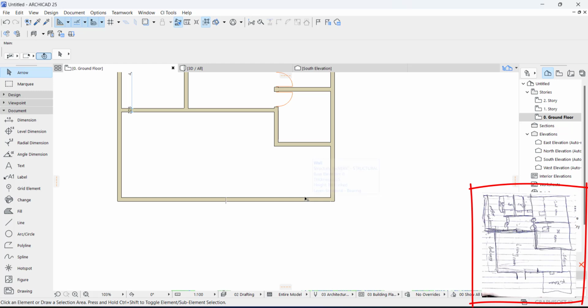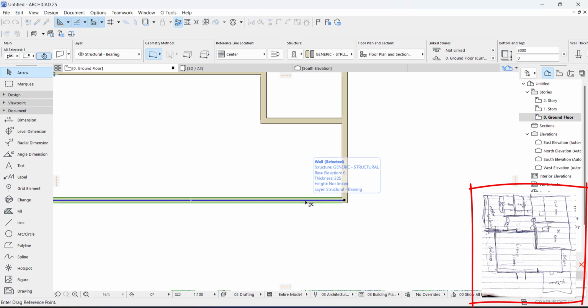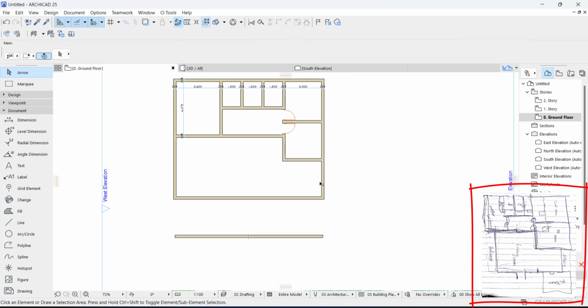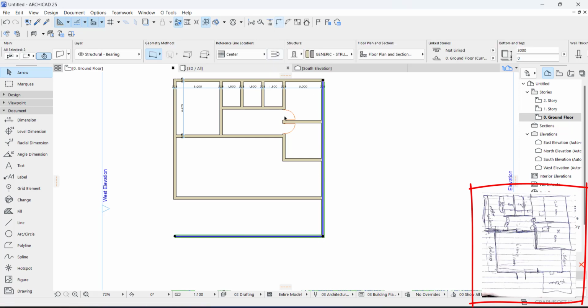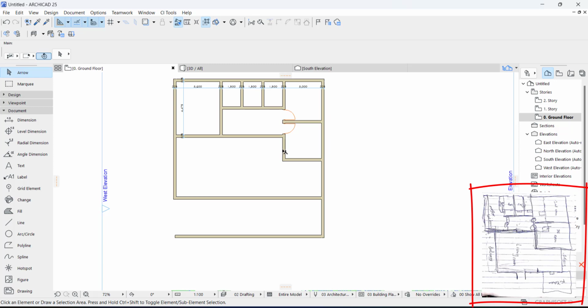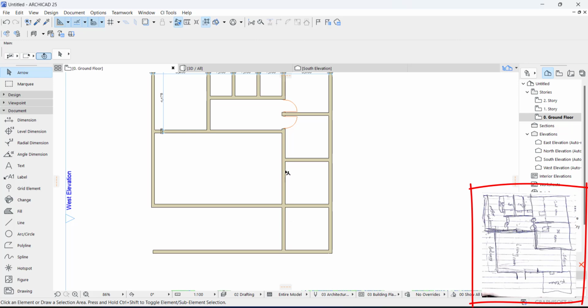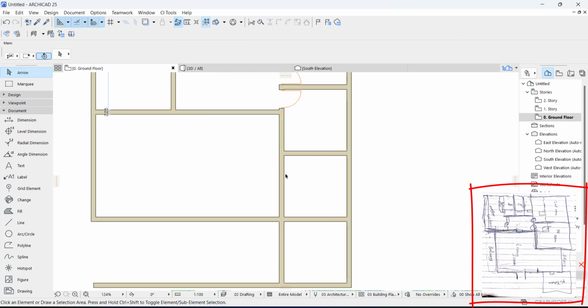Now we are also going to create the kitchen. You said the kitchen is by the side of the dining, so let's create a kitchen. Let's just assume the kitchen is the same dimension, 3225. Okay, so connect this. I believe the kitchen is along this wall, so let's just stretch this wall down to this point. Now you can see that this wall has closed the dining. So what do we do? We have to cut it. Just cut it like so. Hold down your control and click to cut it.